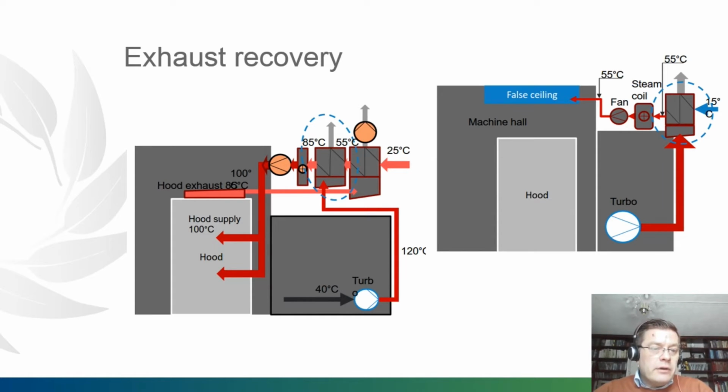Exhaust air can be fully recovered in a papermaking process for water heating or drying section heating. It provides several different ways to lift vacuum system performance to a whole new level. Electric motors are always air-cooled, and in a modern system even that heat is fully recoverable due to a closed motor cooling air system.